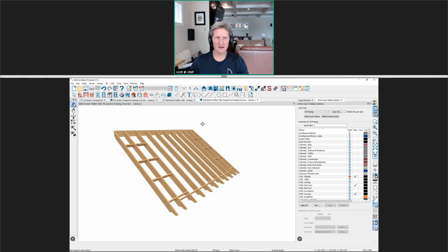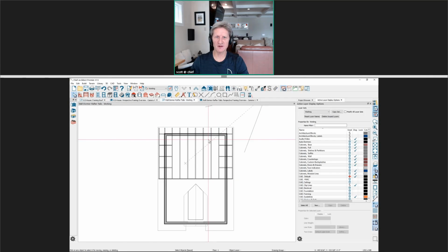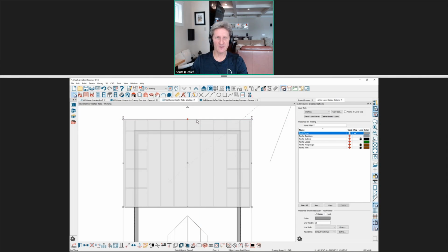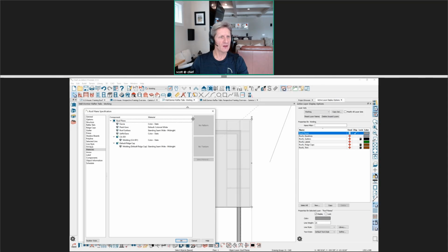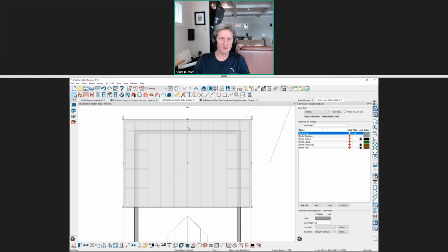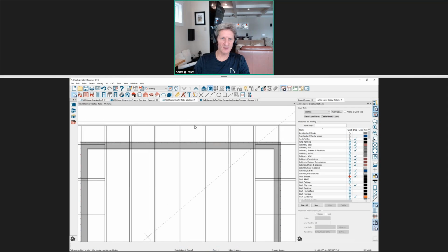Well, let's take a look. Let's move over into the floor plan view for this roof. So here's the roof section that we were just looking at over here. I'll highlight it. Go ahead and open it up by double clicking on it. And over in the structure panel, what I've done in this case, since we have exposed rafter tails, is I've unchecked the eave subfascia. Okay. And so when I rebuild that, let's go ahead and just throw it on there. And then if I rebuild this roof panel and we zoom in, you see it appear in this 2D view, right? Right.